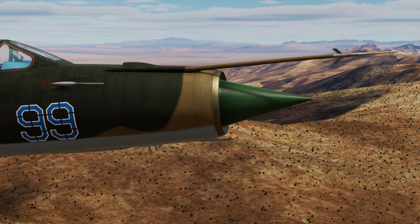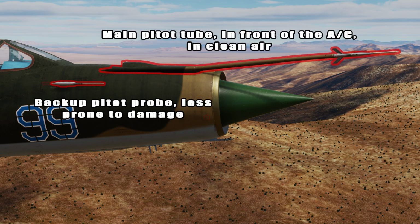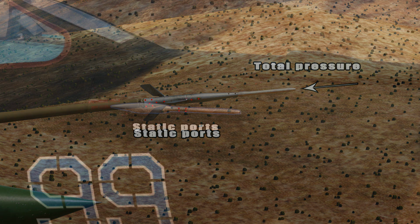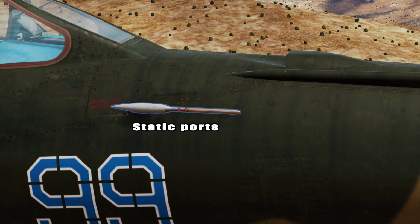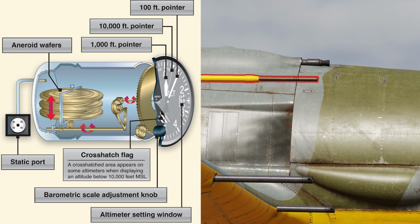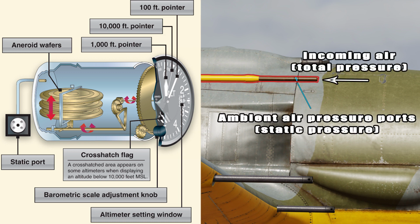The front of the probe will pick up incoming air and feed it to the capsule. This is called total air pressure. The outside of the probe will measure the ambient pressure of the air and feed it to the static chamber. This is called static pressure. The capsule measures the difference between them, something called dynamic pressure, and in turn, turns the needle on your airspeed indicator via a set of gears, or feeds the data to an air data computer.